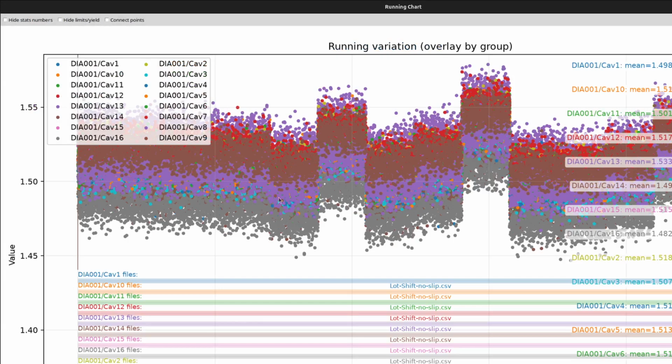And that's because when you insert mold some plastic on top of metal, that metal might be different from lot to lot because they make, say, 7,000 parts or 10,000 parts all at once, and then they'll take it down, put it back up, run it again. So that process introduces its own variation that you can see here in these distinct shifts in the process.